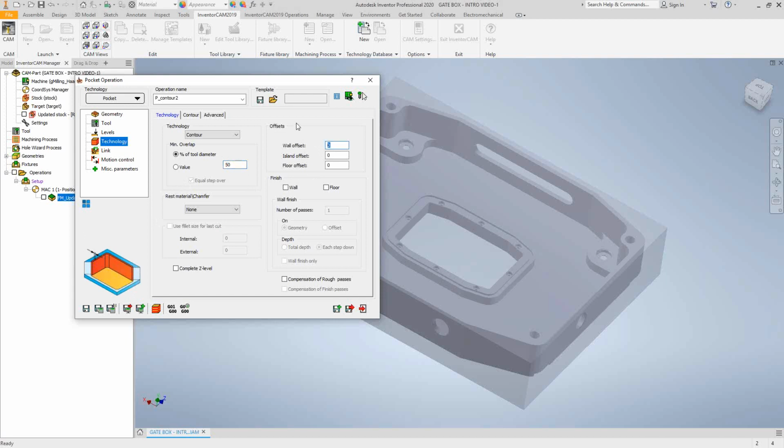If I leave it at 0, I'm doing a finishing pass. I'm roughing out the whole part, though, because there's still lots of material. So in this case, I'm going to leave 10 thou behind. What I could do later is I can use the save and copy option, and then just basically tell it to eliminate that last 10 thou with some changes to my levels and such. But basically, pocketing is both roughing and finishing, just depending on what you check in these options here.